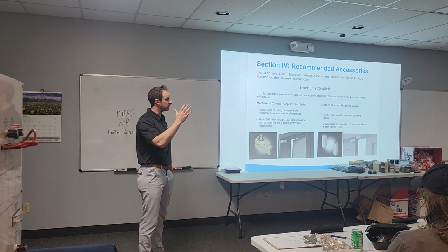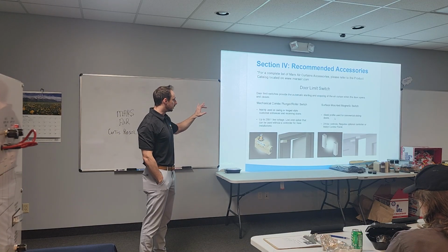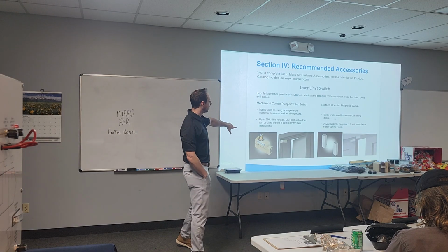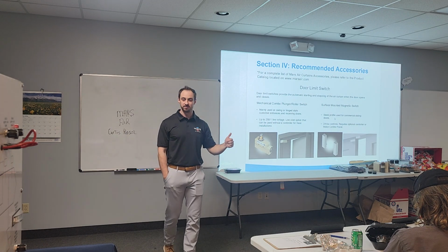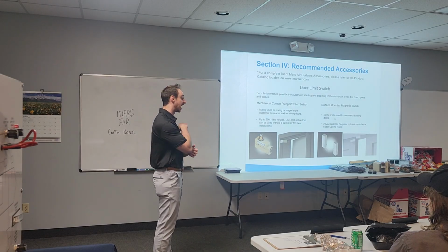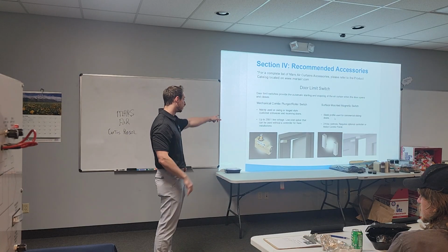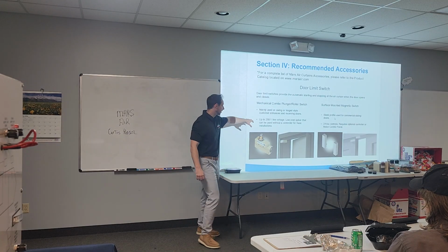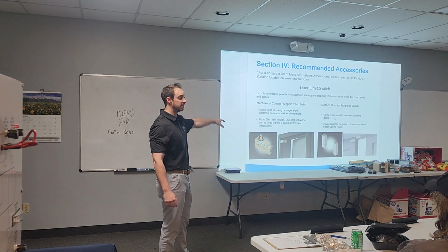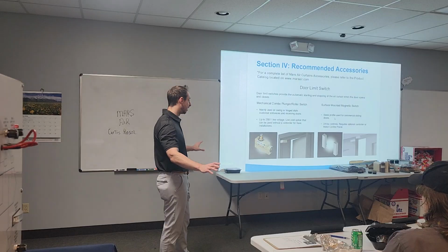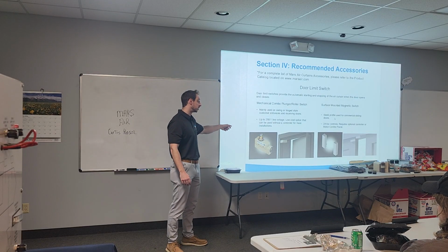So the first one is door switches. Pretty simple, right? All we're doing is turning the unit on and off as the door opens and closes. There are two flavors that we offer. The one on the left is our mechanical switch. I would recommend using these whenever you can, because they're the most cost effective and you don't need a controller. As long as the unit is 250 volt single phase or less, you can tie this directly into the motor line, so you don't need any supplemental circuit. Really good switch if you can use it.